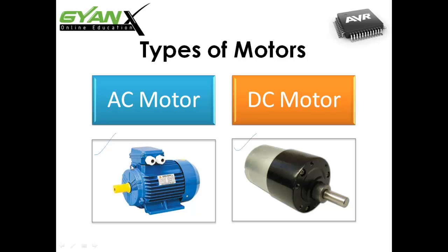The AC motor commonly consists of two basic parts: an outside stationary stator having coils supplied with alternating current to produce a rotating magnetic field, and an inside rotor attached to the output shaft producing a second rotating magnetic field. The rotor magnetic field may be produced by permanent magnets, reluctance, saliency, or DC or AC electric winding. Less commonly, a linear AC motor operates on a similar principle as a rotating motor, but has its stationary and moving parts arranged in a straight line configuration, producing linear motion instead of rotation.